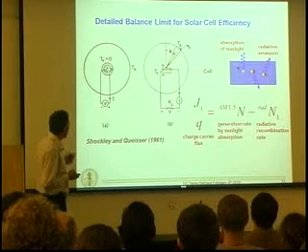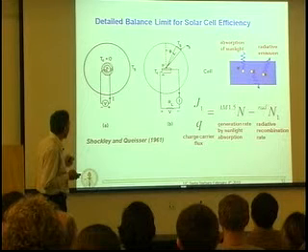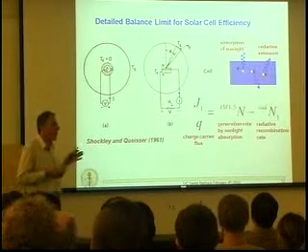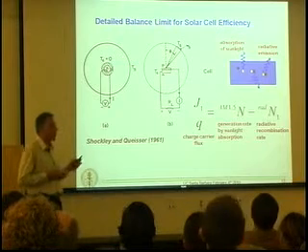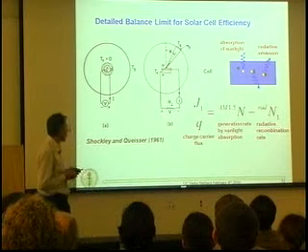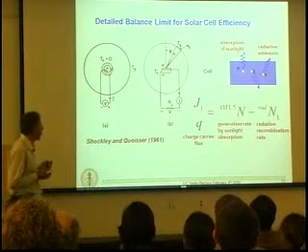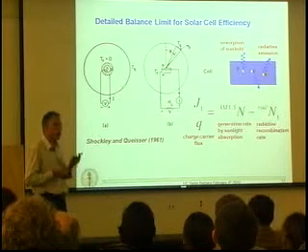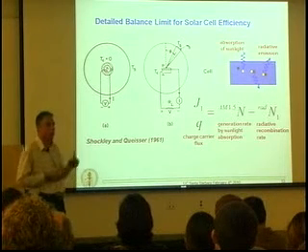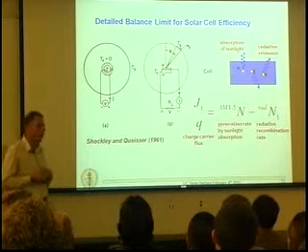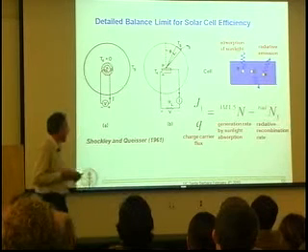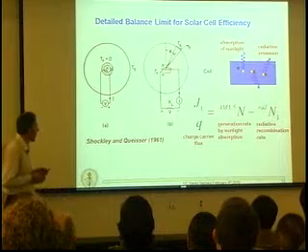A real solar cell, of course, has a finite solid angle from the disk of the sun, and it operates at room temperature. But in any case, once you remove all of the non-ideal conversion efficiency factors by materials purification and device design and so forth, the one limit to conversion efficiency of the charge carriers from the incident photons that you're left with is radiative recombination. So some of the carriers emit light that is then emitted back into free space. So the fundamental limit to a solar cell's conversion efficiency, the radiative recombination limit, is that it is also parasitically an LED. And so we would like to be able to trap the light in such a solar cell.